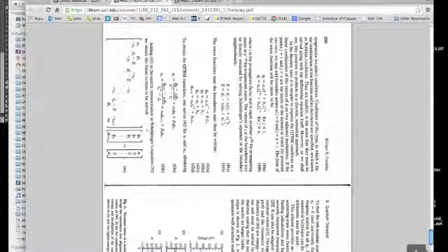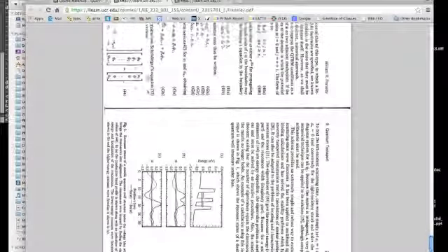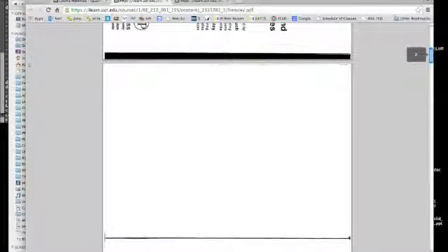Tridiagonal, and then he uses the same algebra we use to truncate the device part of the Hamiltonian. And so you can see what he does here. And this becomes the inverse of the Green function, exactly the same steps that we're going through. So here's the original version. Again, if you want another perspective in terms of starting off with the effective mass equation and using finite differences to get the same form of the tridiagonal Hamiltonian that we get, just going to a nearest neighbor tight binding model.